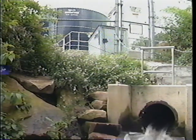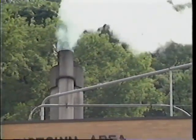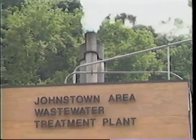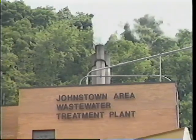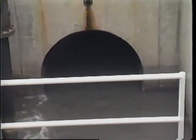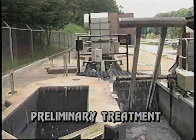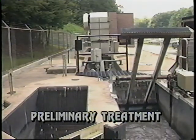Now let's go back and take a closer look at each stage of wastewater treatment, kind of a guided tour of a wastewater treatment plant. But again, keep in mind that treatment plants vary in size and equipment utilization. It all begins here at the headworks, where the wastewater enters the treatment plant, and where screening, shredding, and grit removal are performed, also referred to as preliminary or pre-treatment.